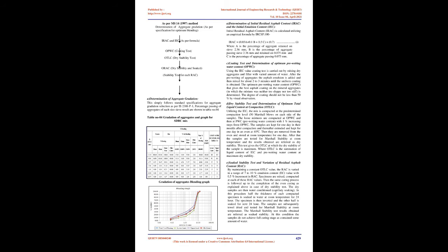Till now there is no universally accepted cold mix design method and therefore no thumb rule that can be followed. Marshall method has been popularly used to design cold mixes. The Manual of Indian Road Congress, IRC SP 100-2014, recommended the Marshall method. The Manual of Ministry of Road Transport and Highways, MoRTH, 2013, 5th Revision, Government of India, Specification for Road and Bridge Works, introduced the procedures for bituminous cold mix as per MS 14.